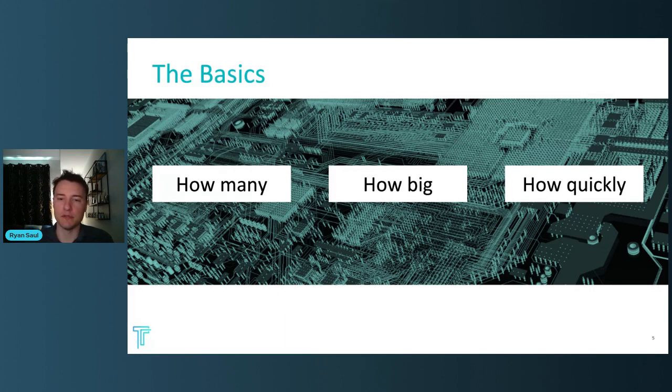or the ordering supply chain professional, because there might be space that's required for coupons for the fabricator to do testing, or tab spacing to allow there to be sufficient mechanical support in between individual boards in your panel.